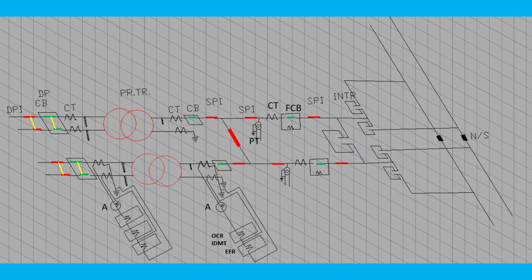It is for transformer protection, but for our OHE fault, in our overhead system, any fault will trip the feeder circuit breaker. And during fault isolation, we close the interrupter during fault condition also, to check whether the fault is permanent or not.